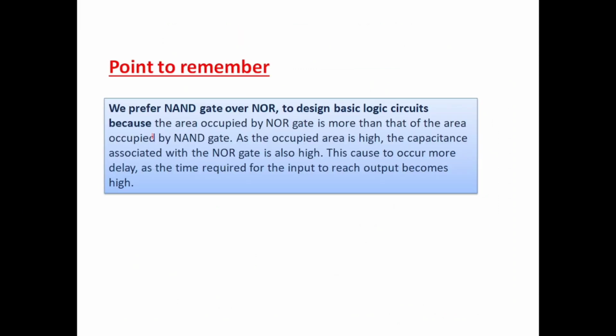Now an important point to remember here. We prefer NAND gate over NOR gate to design basic logic circuits because the area occupied by NOR gate is more than that of NAND gate. As the occupied area is high, capacitance associated with the NOR gate is also high. This causes more delay as the time required for the input to reach the output becomes high. But we know that we generally try to avoid such delays, so that's why NOR gate causes more delay and also covers more area, so we generally prefer NAND gate.